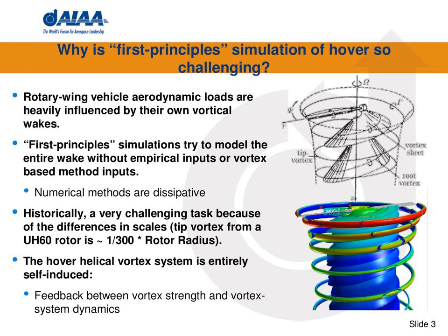outside. If you look at the domain of how much you want to simulate versus the smallest feature you want to capture, which is the tip vortex, which is typically 1/10 of the chord, the range of scales that you need to model is large. And that means a lot of grid points, and you need to be very accurate.